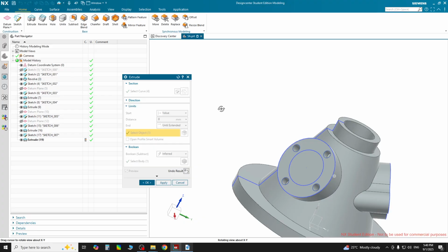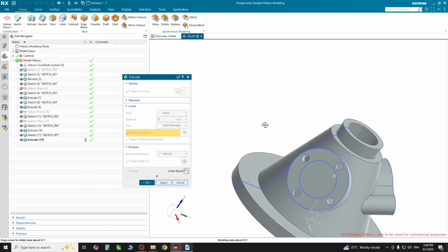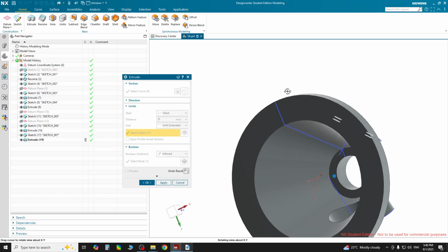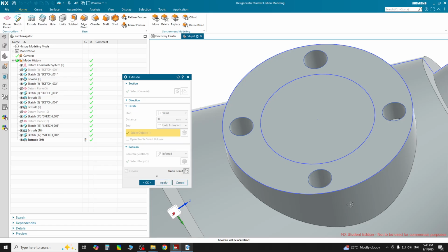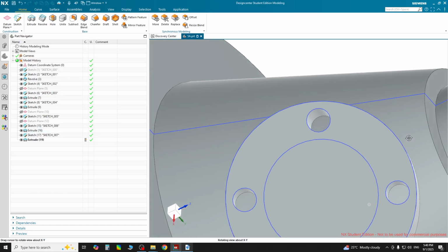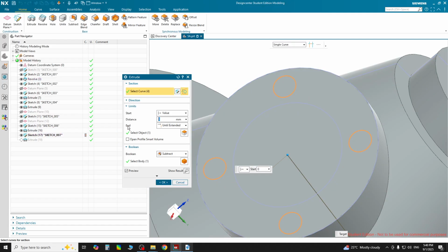So it will be until extended mode to take the whole variable length up to our need, meaning the first surface. So to do this, we need until extended. We have to select here until extended with subtract mode.